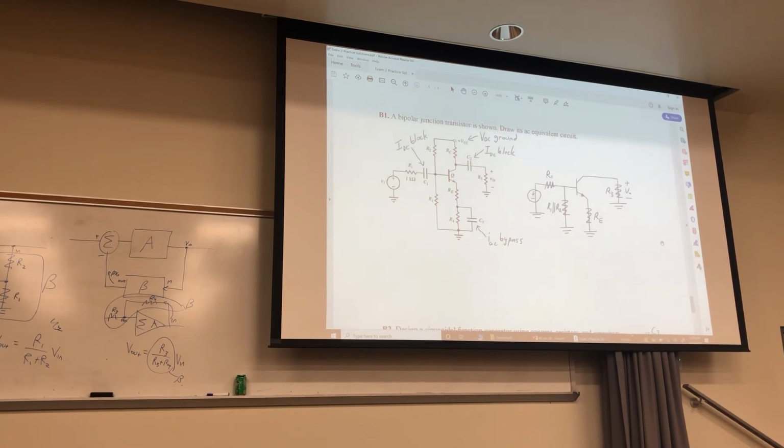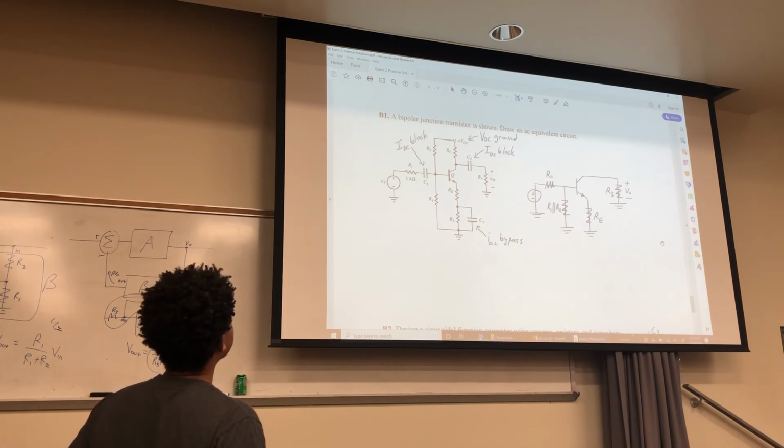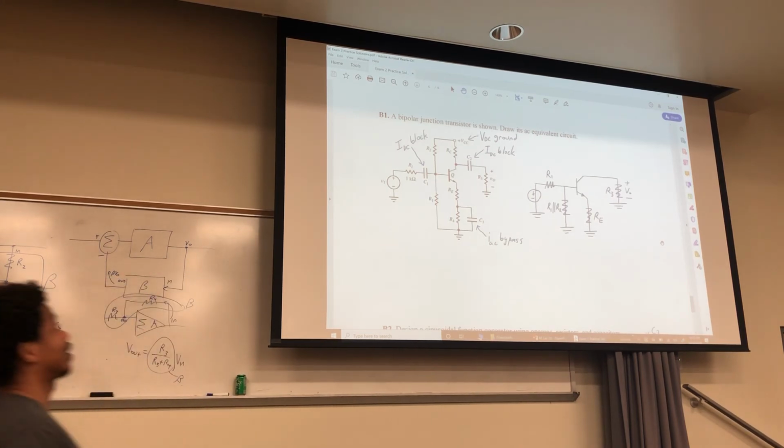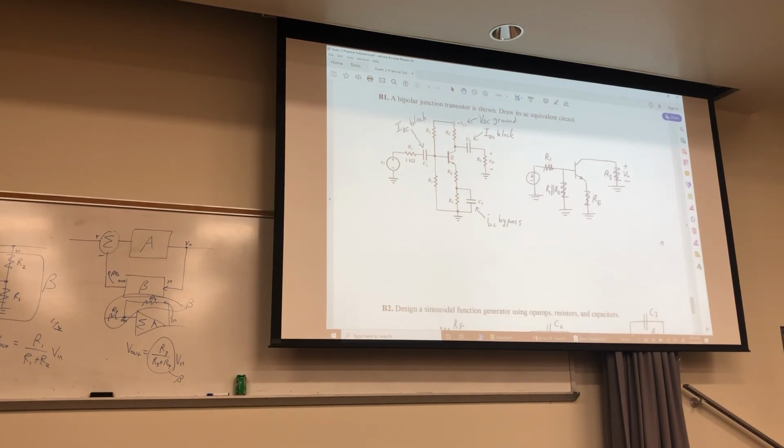For the alpha loop now, would you also have RC in parallel with R3? Yes. Yes. And I didn't do that. Thank you. Another point. That's probably like 5 points. Yeah, so what he's talking about is that RC right there should be in parallel with that because that's ground. And I didn't do that over here. Okay, so yeah, very important point to make.